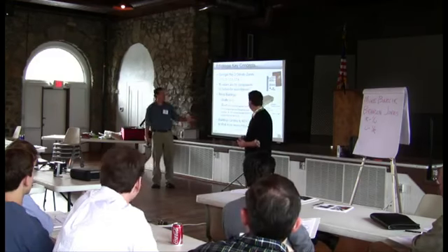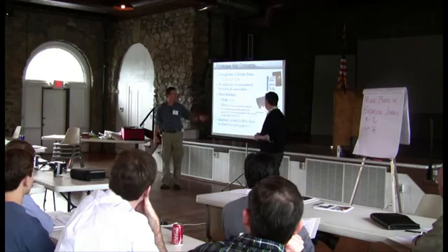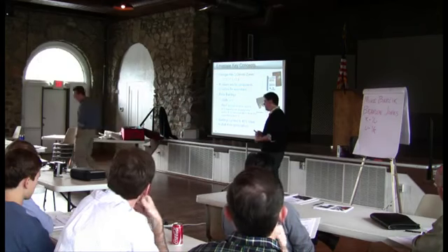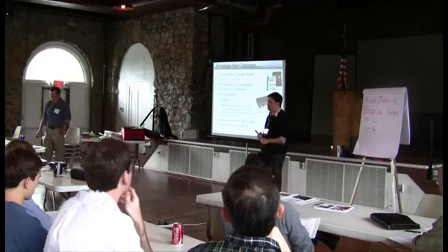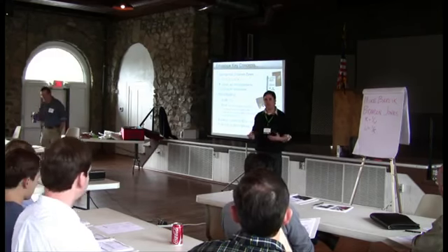Basically, the walls are, I think, pretty easy. I think the walls are 13, if I remember right. I'll have to check. We'll get to the code in a second. Finally, if you're going to go the prescriptive or really the simple trade-off route, your building can have no more than 40% glazing as a percentage of the wall area.